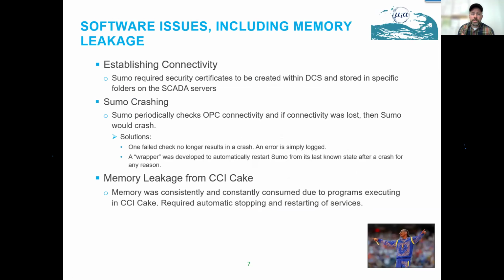And I think a lot of these issues that you're going to see here were really on HRSD. I don't mean to blame the vendors for any of these things. So even after we got connectivity between the DCS and the digital twin after that year period, we still had brief interruptions in OPC connectivity, or open platform communications connectivity. And so even when we had a brief one, the digital twin would crash.